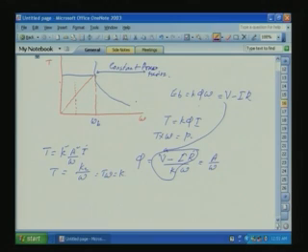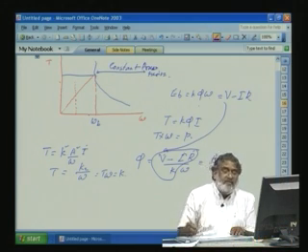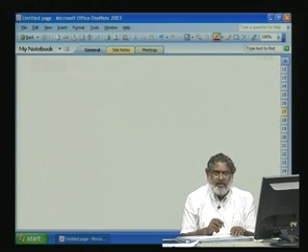Dynamics may not be as fast as possible, but we can have speed control in all four quadrants and all regions, below base speed and above base speed also. So how was it done? Initially we sought resistance control, but resistance control is not economical, its efficiency will come down. So we are not using resistance for speed control. How can it be done? Let us say one very famous system, introduced around the 1890s, the Ward-Leonard system.